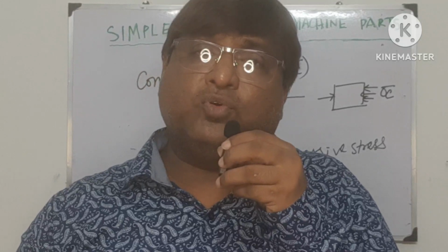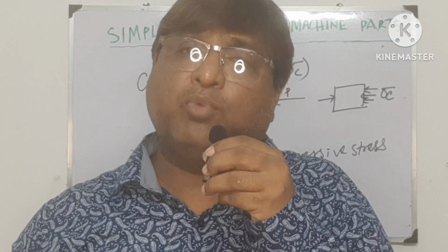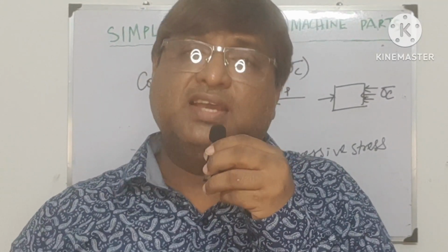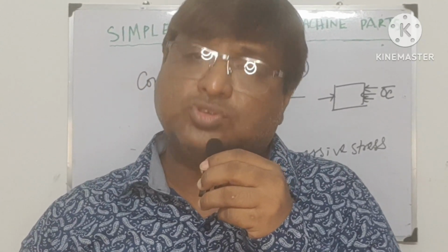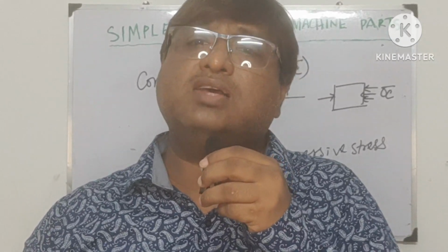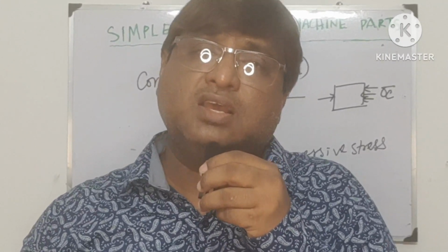Now we will discuss Hooke's law. When the external forces or load act on the body up to the elastic limit, stress is proportional to strain. That is called Hooke's law, and from this Hooke's law we can get the Young modulus. So how do we get Young modulus? Just see.